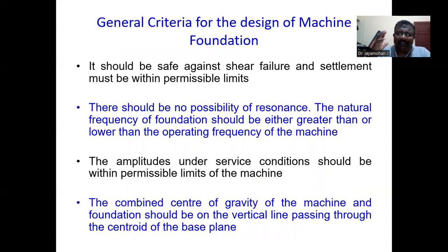Now, the general criteria for the design. As in the case of foundations subjected to static loads, here also the foundation must be safe against shear failure and the settlement must be within the allowable limits.